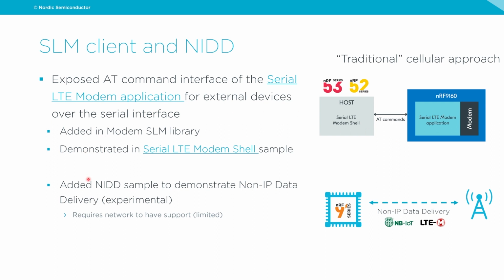And we have also added a NIDD, which is non-IP data delivery, sample, to demonstrate how that can be achieved. However, support for this feature is rather limited at this point in time from the network operator side. So if this is something that you're interested in using, do check the support for the regions where you want to deploy your product, whether this feature is supported or not on the operator side of the link.